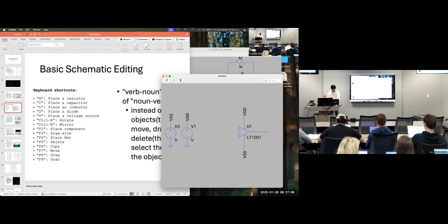So in my inverting amplifier schematic, what do I draw for the positive terminal of the op amp? For an inverting amplifier. Ground, exactly. So I'm gonna just put a wire here, maybe I'll make it go down 90 degrees. Done with that, press escape. I'm gonna press G for ground. Like that. Boom, we got a ground terminal. Pretty nice. Okay. Now let's do our negative terminal.